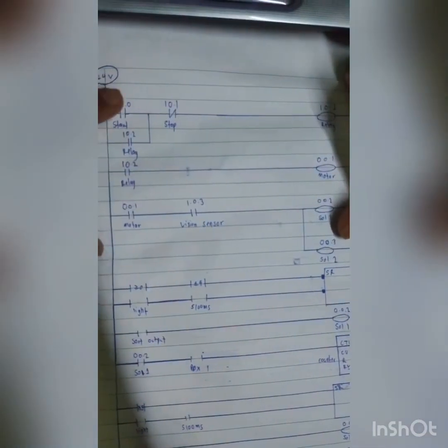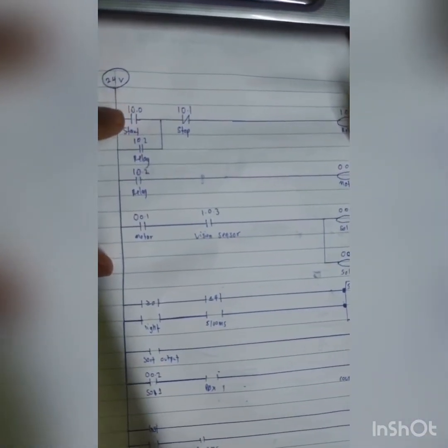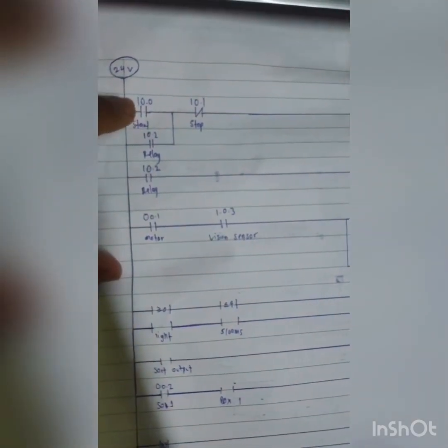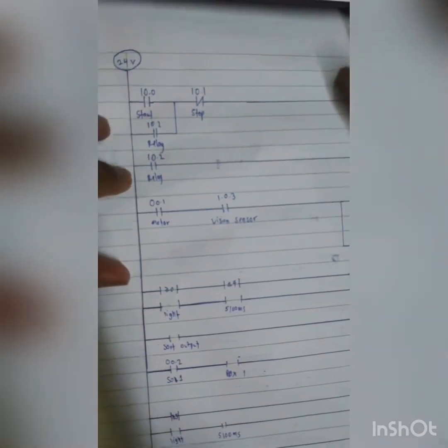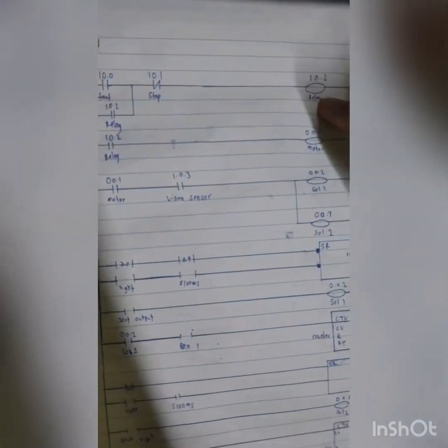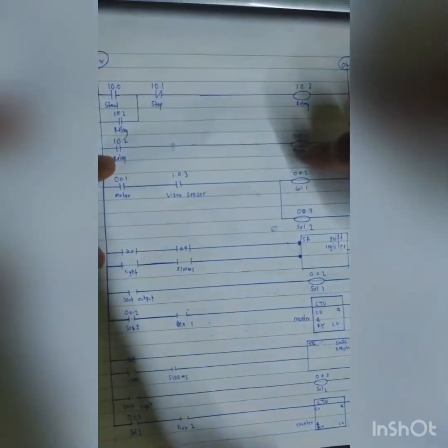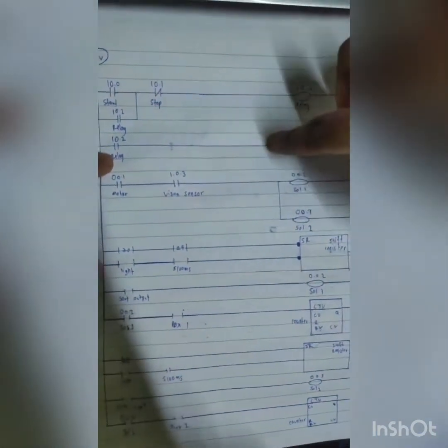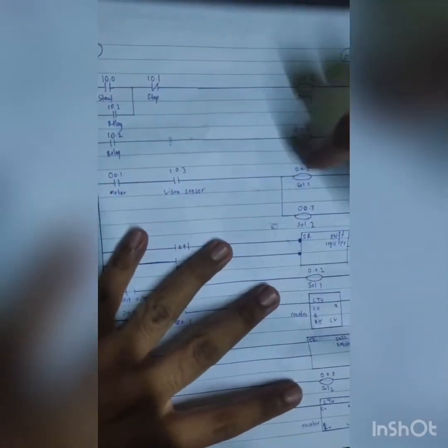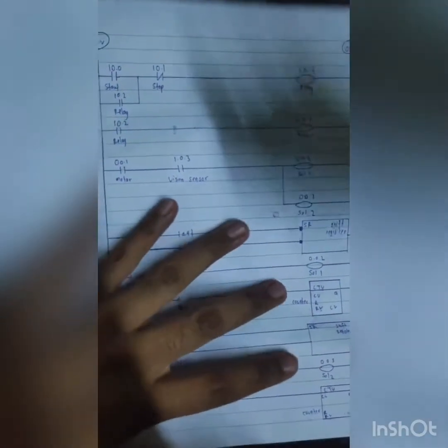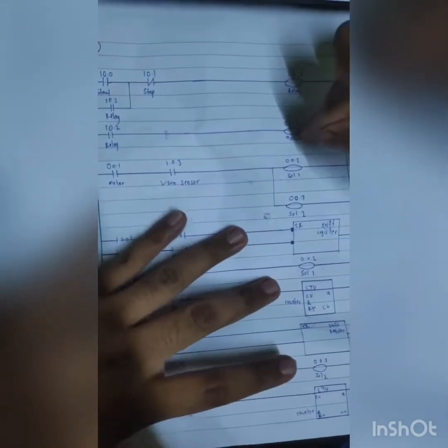Once we press the start button, our sorting machine will run. The second lane is when the relay functions. This relay will energize so that it connects to the motor, so our motor will run. This motor running moves our parcel on the conveyor, so our conveyor will turn on.